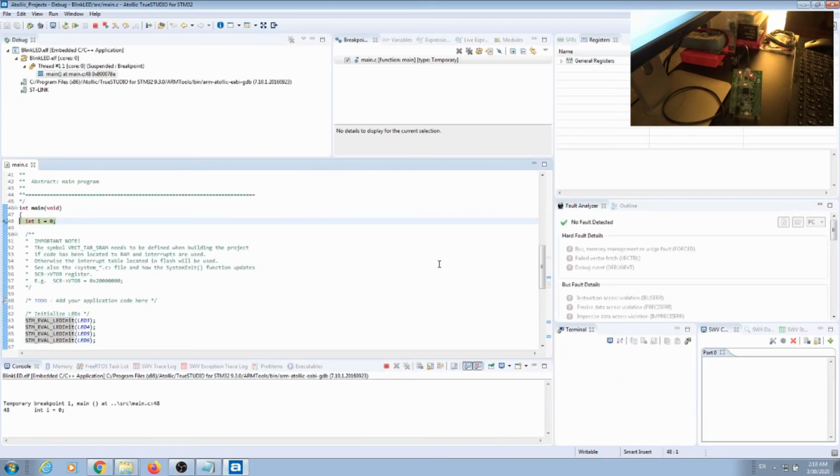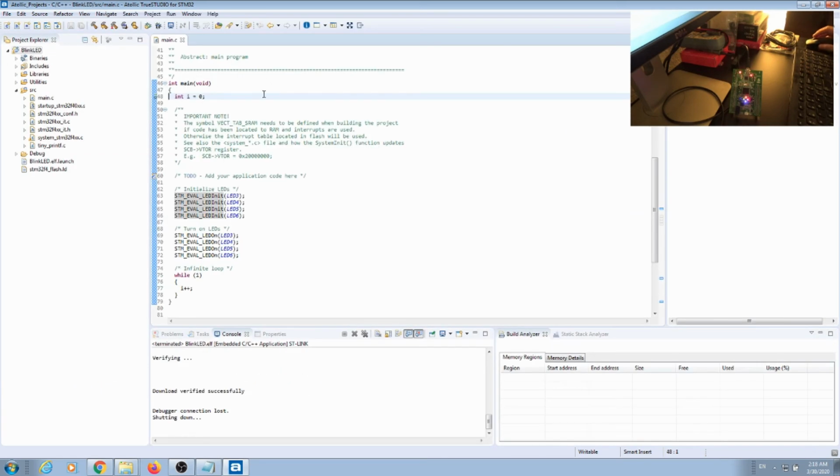So it changes the development environment a little bit. Now I have access to registers, variables, and your code over here. Notice that the code is ready to execute, it's waiting for you to give the command to start, and that's done using this Resume. I press it, and as you can see, the LED is turned on, the code is up and running. If I press Terminate, the development environment goes back to the programming mode, but the code is still running inside of your board.